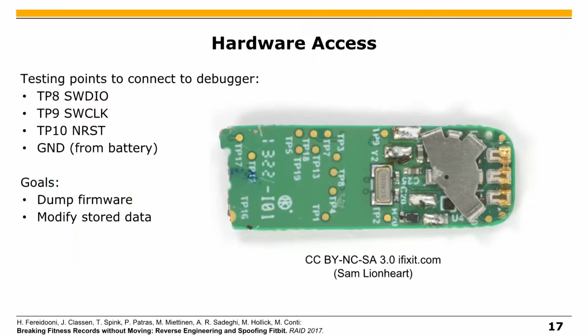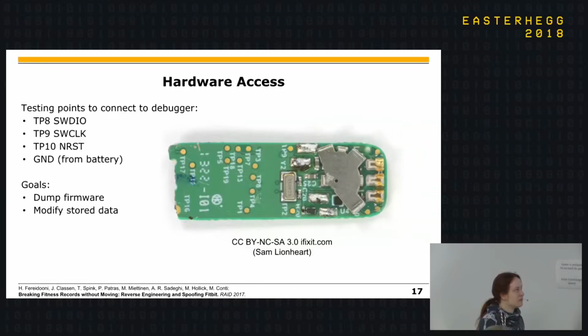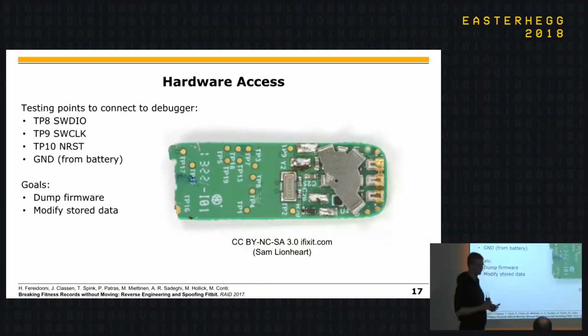So the next step is that we took apart the Fitbit, and this is what comes out. Ours looked a bit better, so here the guys from iFixit broke some antenna stuff over here, but it's a very nice picture. And for us, the most interesting thing was the SWD protocol. With SWD, you have full access to the microcontroller and also the complete memory. So if we want to know what's inside the firmware, we want to get SWD access.